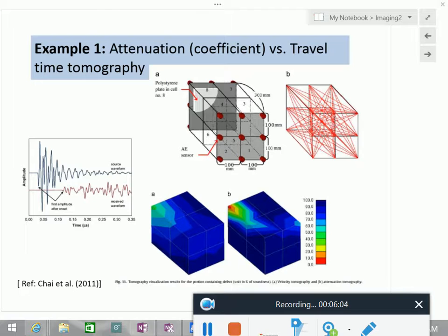I said something else too last time. And the coupling and pressure. Exactly. So if you have more coupling, it becomes better. If you just press the two transducers together, and for whatever reason the pressure on the back of one of the sensors is more than the other one, it looks as if the attenuation is actually less, which is not true.